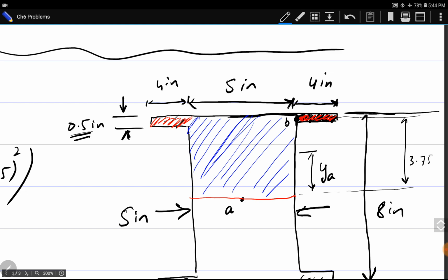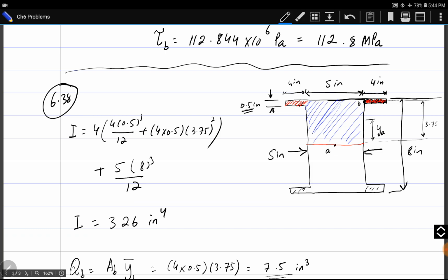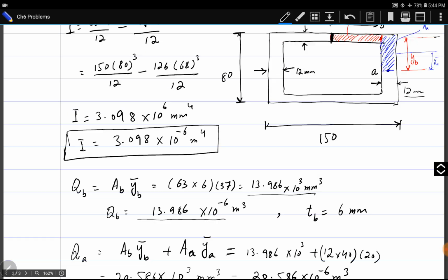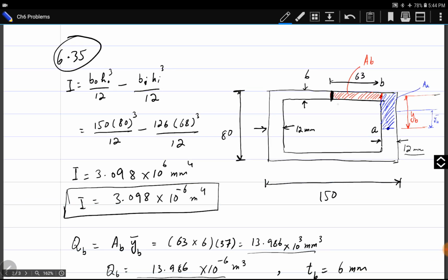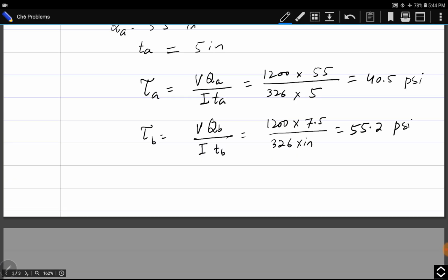In an I section, the shear flow starts from this point, grows, merges and reaches the centroid A. For the box section in the previous problem, it starts from the midpoint and splits in two directions. Whichever point is asked, we just need to consider the area from zero till that point. I hope it was understandable.